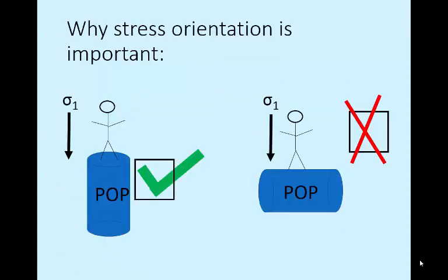The orientation of openings is one area in which a rock mechanics engineer may consider the direction of maximum stress. Think of a can full of pop. You could probably stand on top of it without damaging it. But if you try to stand on it sideways like on the right, it will guaranteed break. So if you could choose the orientation of a tunnel underground, and that tunnel is needed for a long time, it might be wise to line it up in the direction of the maximum stress and not minimum stress.